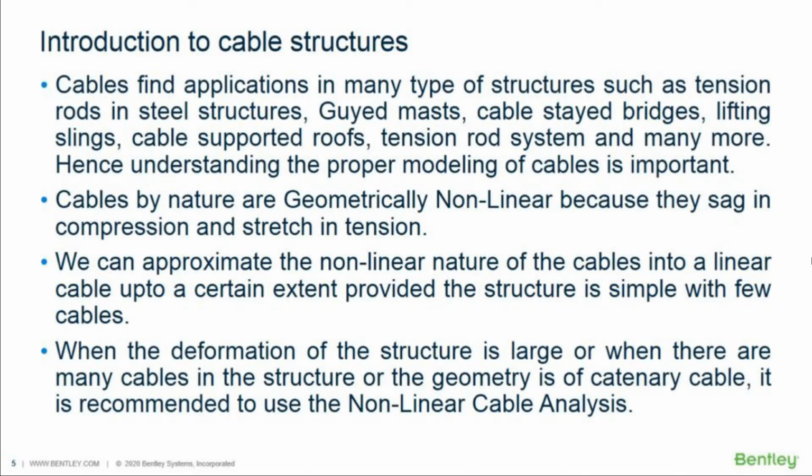Cables by nature are geometrically nonlinear because they sag in compression and stretch in tension. Even though cables are nonlinear in nature, we can still approximate the nonlinear nature of the cables as a linear cable up to a certain extent, provided the structure is simple with few cables only.